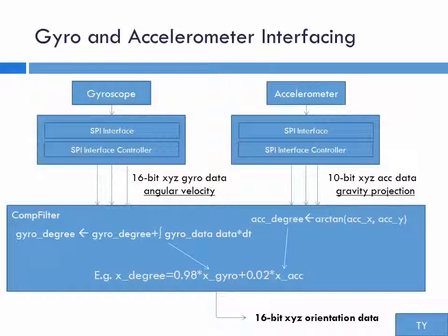This is simply done by giving a dominating coefficient to the gyro and a small tuning coefficient to the accelerometer. Note the 2 coefficients always sum to 1. The values shown here are for demonstration purposes only. Experiment with different combinations for optimal results.